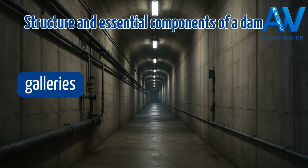Inside the dam, there are also galleries. They allow personnel to move inside the structure, inspect it, monitor cracks, check drains, and sometimes access instruments. These galleries are the technical heart of the dam and provide direct visibility into its condition.